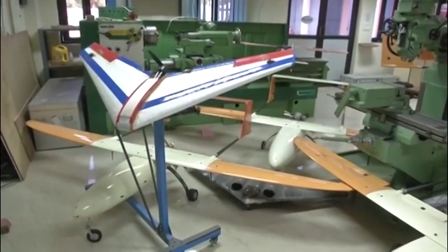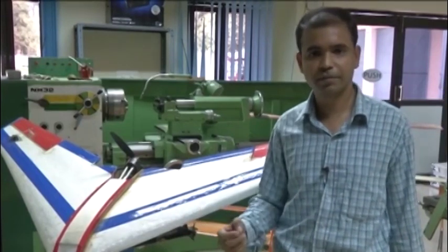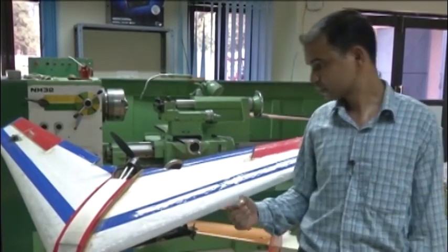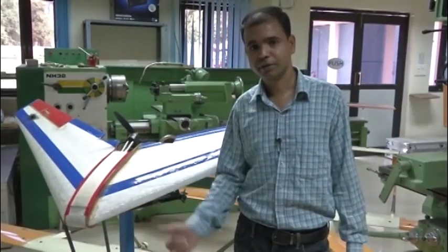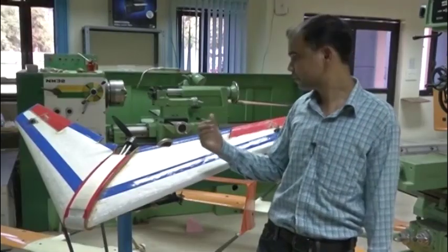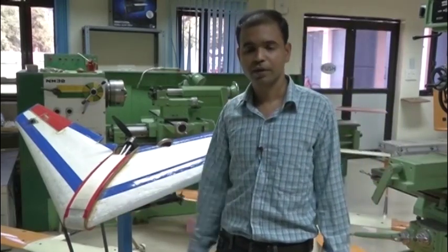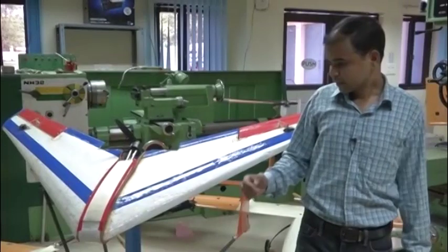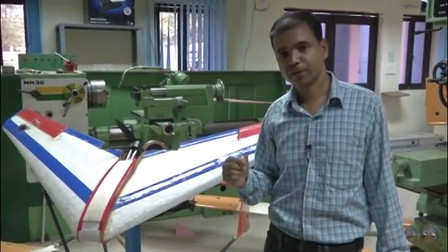As you already know, for an aircraft to be stable, our aerodynamic center must be behind the center of gravity. That we can achieve by adjusting the weight distribution. If our aircraft is unstable, it doesn't mean it cannot fly. It can fly by giving some suitable feedback into the control surfaces, like our body is unstable to move on a road, but we can move. At the same time, our requirement is to trim our aircraft at positive angle of attack.